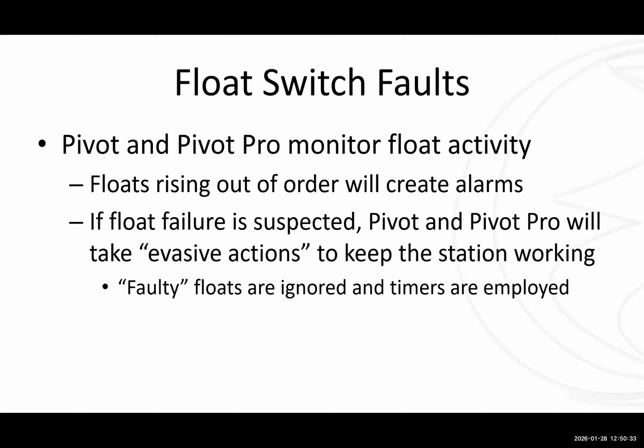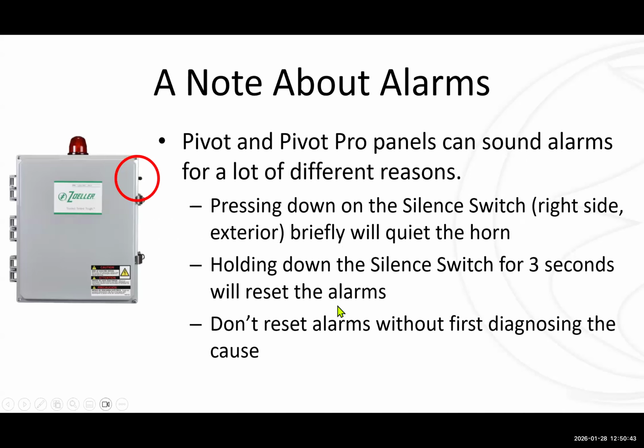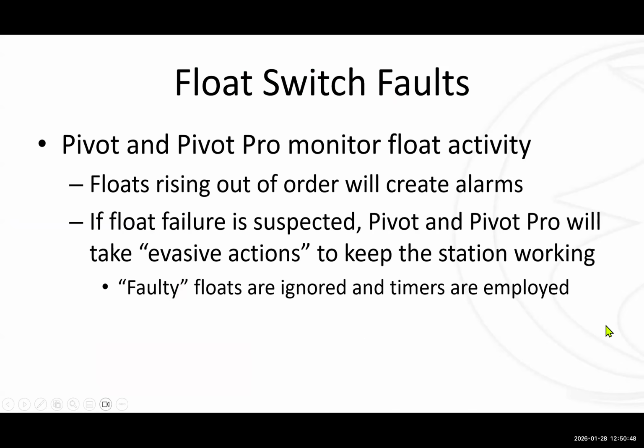Like I said at the very beginning, we want to prioritize running the pumps. The last thing we want is some kind of an overflow or a flooding situation. So, for instance, if the low float in a tank, the stop float, does not come up, but the next float up does rise, then the control panel's firmware makes the assessment that it can no longer trust that low float.